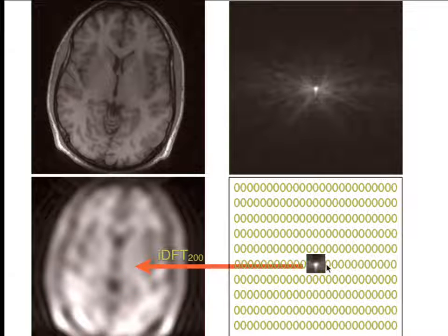I get a bigger image, but I don't get more information. It's still low resolution. That is exactly what's happening when you zero pad a signal. You cannot resolve frequencies better, but you just zoom in. You kind of just display them on a bigger screen. Okay?